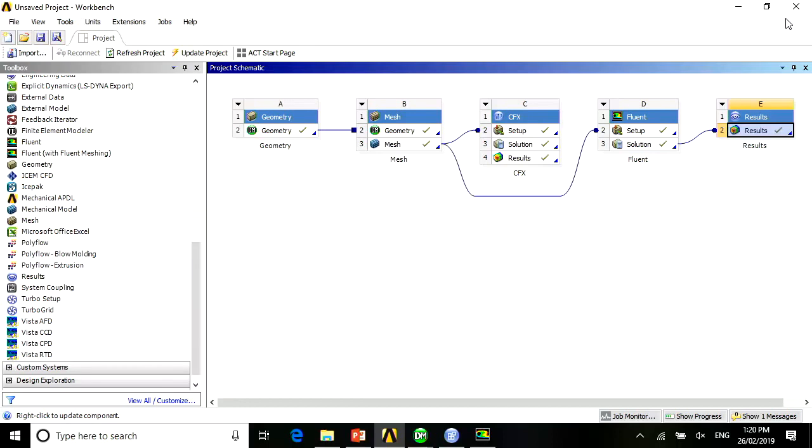Assume the same boundary. CFX tends to assume that you're always solving a fluid problem, so you are treating your geometry as walls and everything is hollow inside. It's assumed hollow. For the fluid, you have to change it to be hollow. Fluent always tends to assume it's solid.